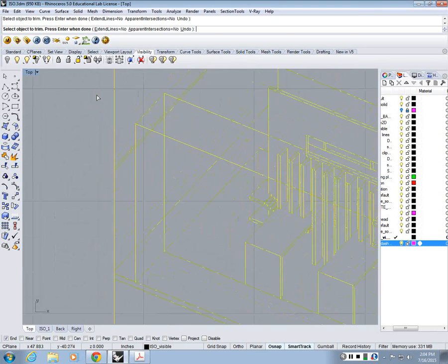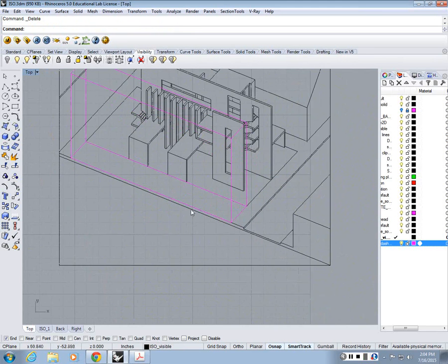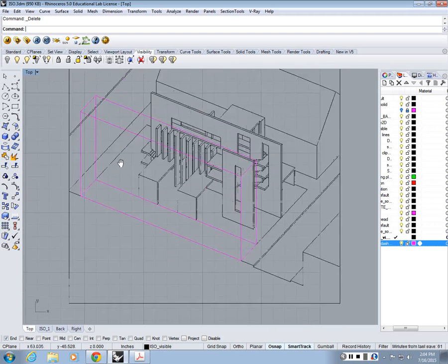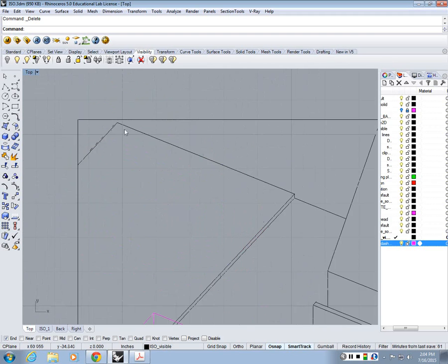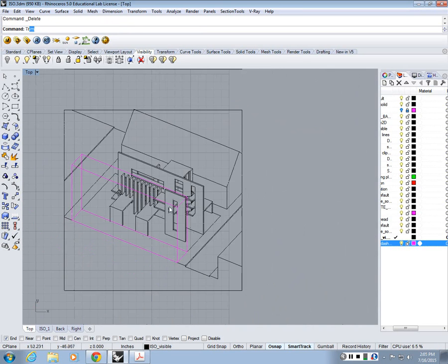So I cleaned these edges. So basically I'm going to hatch this part as black, right? So I can delete this line now. So this will be a black hatch because it's ground, right? And this is going to be background, so I extended this line. So I typed in extend, extended this guy and deleted this guy. So this will be one hatch, this will be another hatch, and then I could do my styling on my drawing.